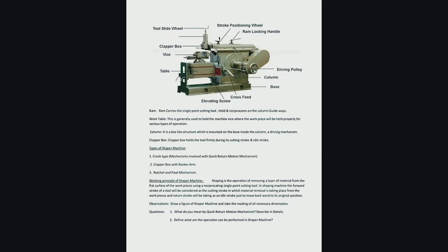Angle of action of cam can be defined as the angle moved by the cam from the beginning of ascent to the termination of descent. Classification of cam: cams can be classified as follows. 1. Disc or plate cam. 2. Cylindrical cam. 3. Translating cam. 4. Wedge cam. 5. Spiral cam. 6. Heart-shaped cam.